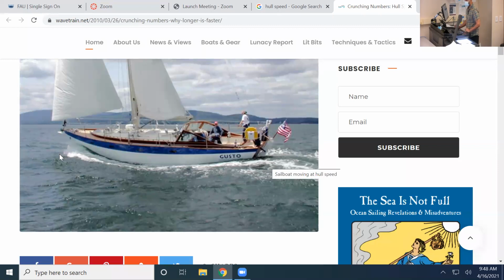So this is a very specific speed, right? If your boat starts going faster, what will happen? This upwelling will be behind the boat, right? If you're slower, then instead of one full sine wave, you get multiple sine waves inside. So this instance is called the hull speed, and this is one of the most efficient speeds to go at. Okay, you tell me why. Why is this a good state to be in?